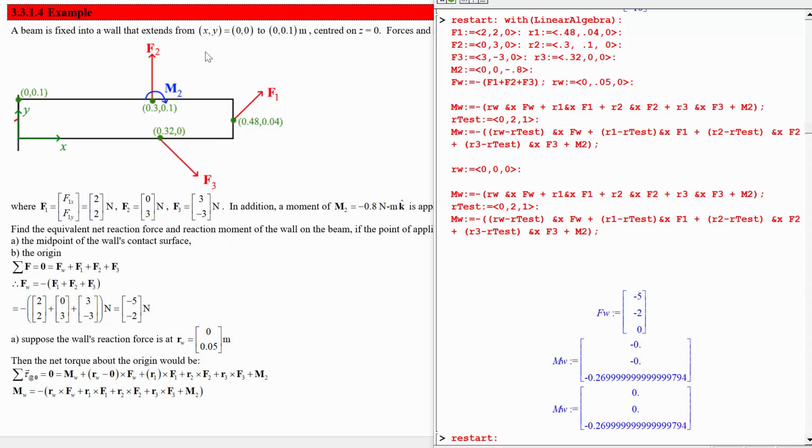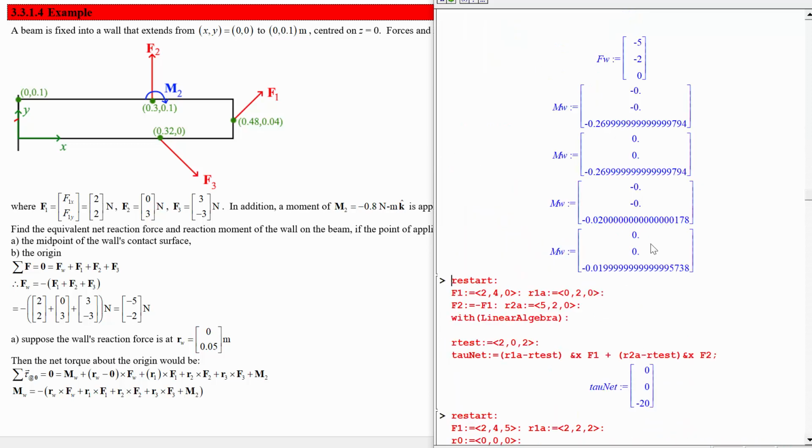The net force is mostly over to the right and up a little bit. And that means that if we were to shift the reaction force down and apply it lower down, we'll probably have less distance for the couple that the reaction force creates with this net applied force. So that means that the wall moment should be lower when we say that the wall's reaction force is lower down on the wall. And let's check.